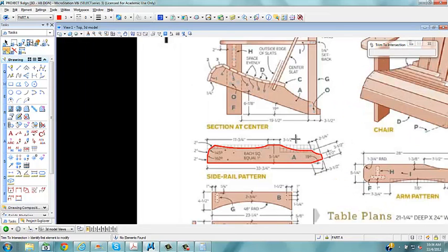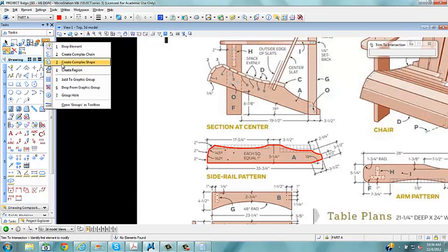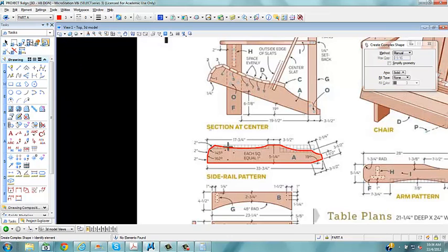So basically we've got our shape now that we need to make into a complex shape. Right now we're just a series of line segments, so we're going to go to our 6-3, create complex shape. This is in a 2D element, and we can set this to automatic, so it's just going to automatically find endpoints. So I left click on one line, just move my mouse over to the left side and just keep left clicking, and you see how everything connects into a solid shape. And I just left click one more time, and now that whole thing is a shape.